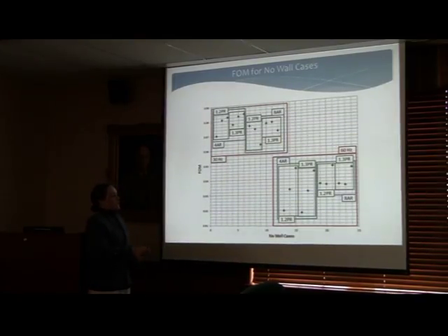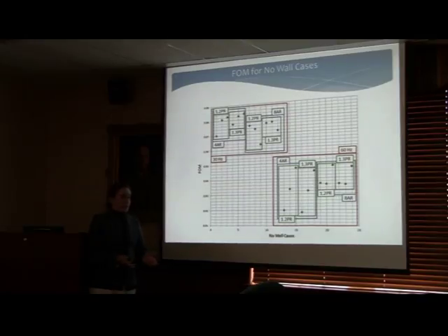This breaks it down for anybody who needs to run, say, a 4-aspect ratio pulse tube and wants to operate at 60 hertz, to see what the trends are going to look like. You can see within each set there are established trends, some of them different than others, but there are definitely strong trends. Usually, with the exception of this area over here, the 1 gram per second mass flow rate at the inlet operates at a lower efficiency than the 3 and 5.